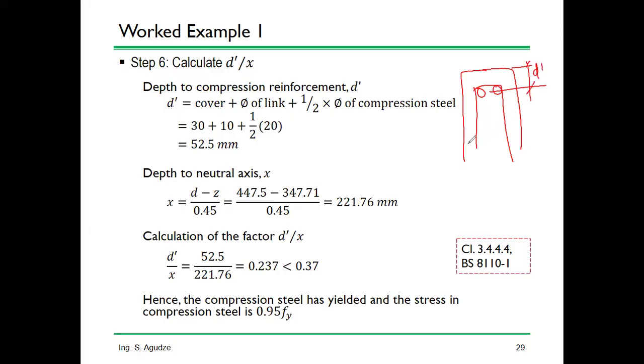Now, in terms of assuming the diameter, typically because the reinforcement in the tension zone would usually be more than that in the compression zone, we sometimes assume smaller diameter for the compression zone compared to the tension zone. But if you assume 25 for tension zone, you can still use the same 25 for the compression zone. There will be no problem. Okay? Your assumption should be reasonable.